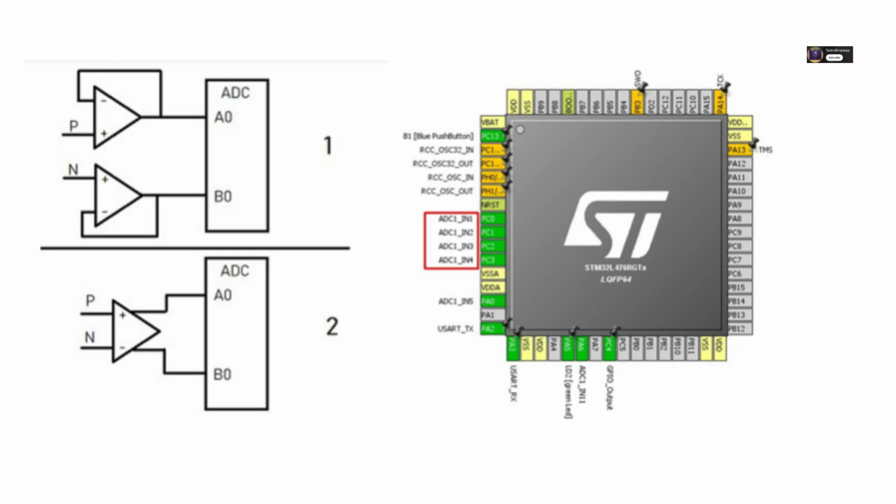Why would you use differential? Differential inputs are fantastic in noisy environments. Because they measure the difference, any noise that affects both input wires equally gets canceled out. It's great for rejecting common mode noise.